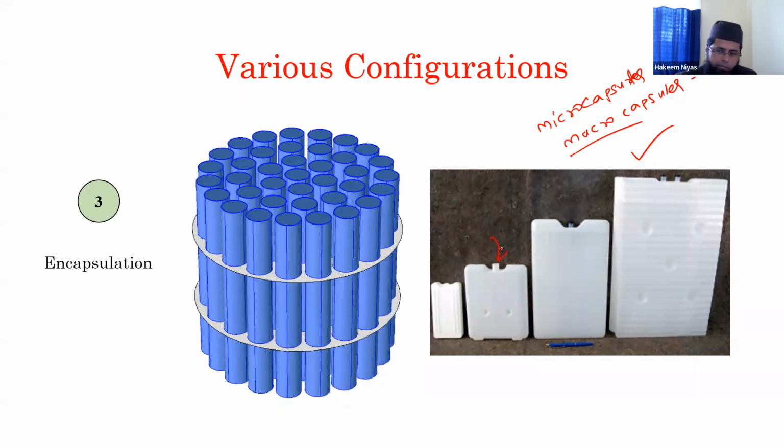Normally, whenever we fill the containers, we have to fill with liquid state PCM, so that it will reach all the nooks and corners of the container. Once the PCM is filled and it solidifies, a small contraction is possible, like 5 to 10%, the volume will be reduced.